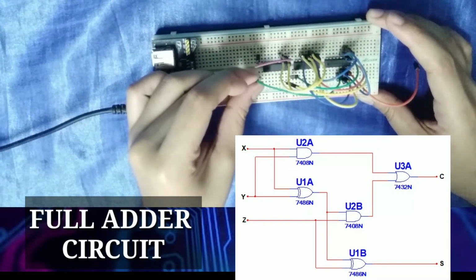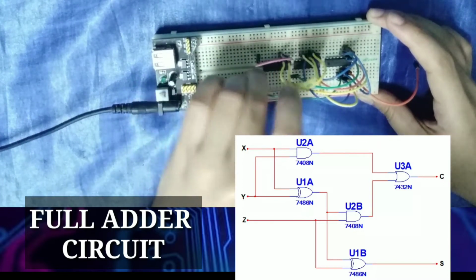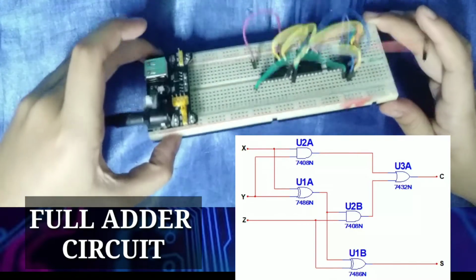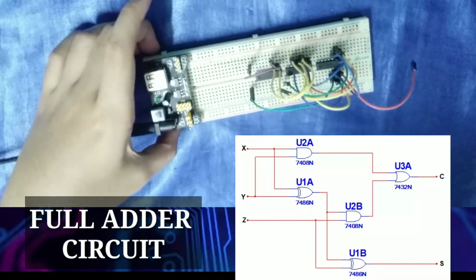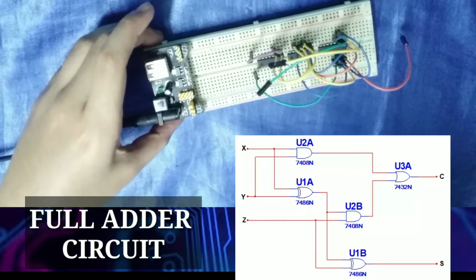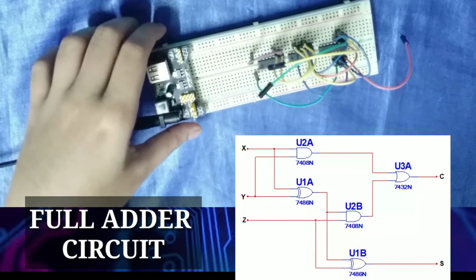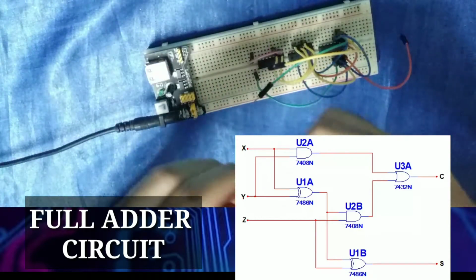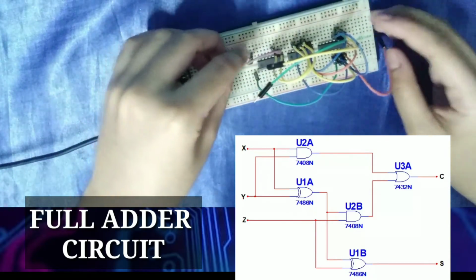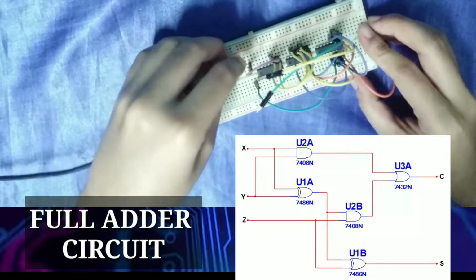And let's connect it here for our LED outputs. And of course, for our outputs, let's not forget our 360 ohm resistor here.